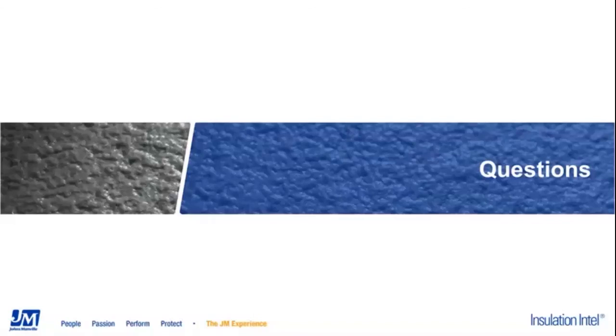And then inevitably they come back and go, well, yeah, that was the product we were switching out of. And it's like, well, that's one of the reasons to follow that changeover procedure, so that you have that water scrub on the B side and you're absolutely certain that you don't have that residual material resting in the lines to potentially cause you some problems.